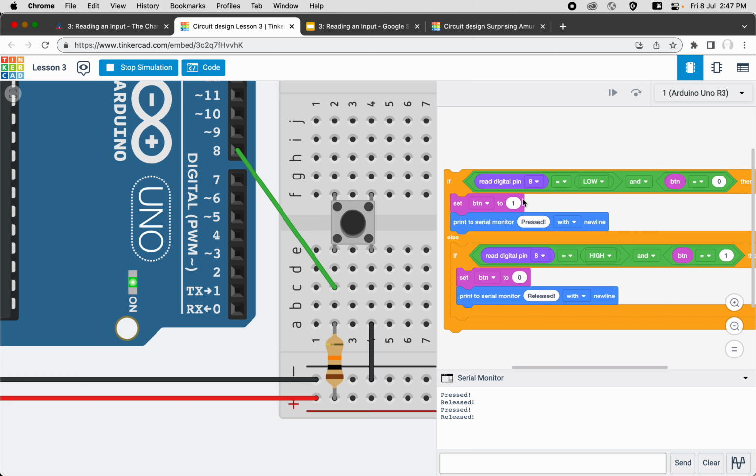So you remember that the previous state was pressing it, and it will print out press. Then when there is a change in state again, if the button is equal to 1, that means previously you were pressing it, and now you are releasing it. It will change the state, remember it, and update the status. So that is how this is done.